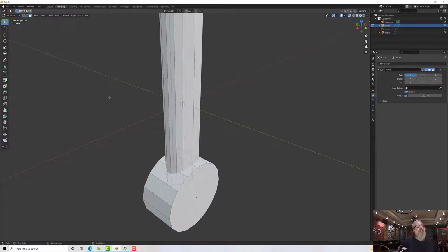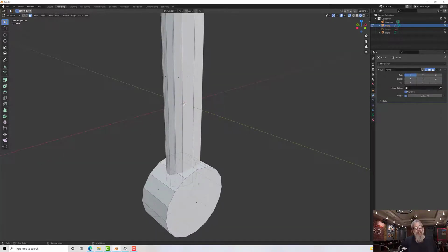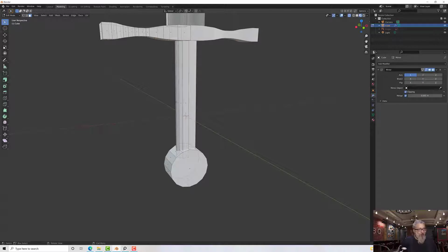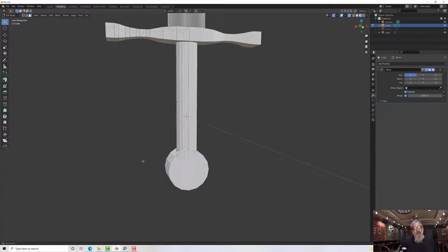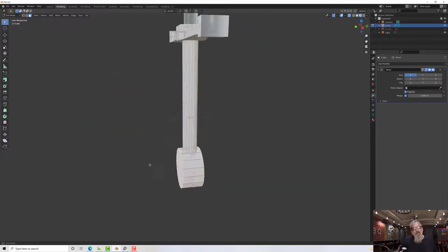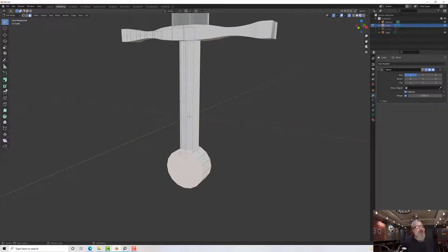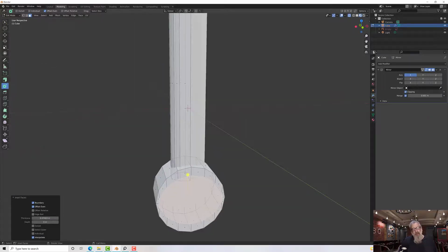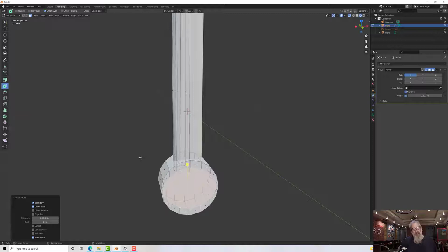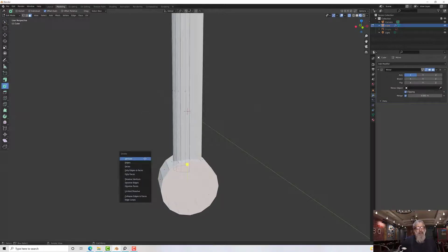So I'm going to go to edge for faces first and select my face. So let's go to W and select faces front and back. There we go. And this time I want inset. So if I click on inset and then drag my piece, it's not really behaving as I would expect it to. I'd expect it to be just insetting and just working. So perhaps it is messed up. So what I'm going to do is delete that face.